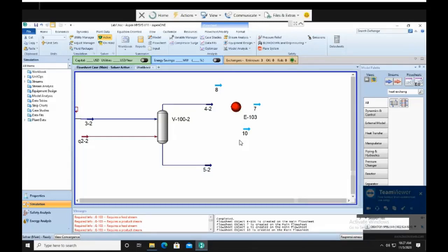the heat exchanger setting is a simple weighted type, pressure drop shell side 10 kPa, tube side 35 kPa. The heat exchanger 102 uses refrigerant 114 as cooling medium. You may use Peng Robinson for the fluid package for refrigerant 114. Okay, now I've given you the spec for refrigerant 114. So we don't mix the refrigerant line with the main line.